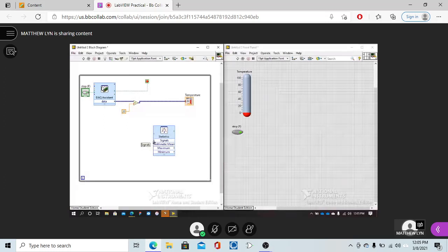So right here we have a potentiometer. See that? So basically it's a 1K part, right? On one leg, we are going to attach the power source here, and the other leg, we are going to attach the 0 volts, and then the middle pin, we're going to send to the input where we did select the voltage input. There.